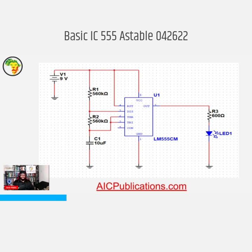So first, let me explain what we did with this circuit. Up in the left-hand corner, you're going to see everything is powered by a 9-volt battery. Then we have R1, which is a 560K ohm resistor. And we have R2, which is also a 560K ohm resistor. Both of those run in conjunction with a 10 microfarad capacitor.